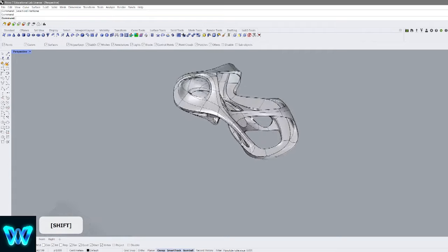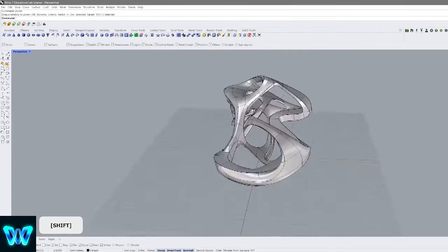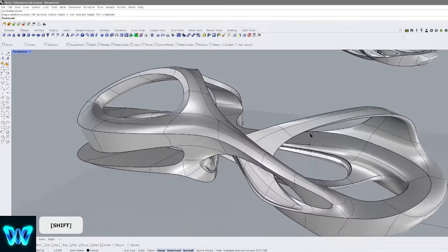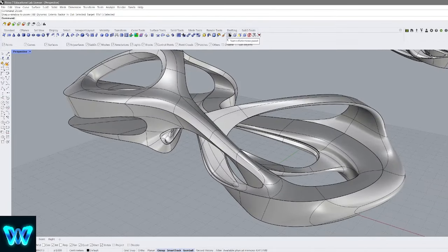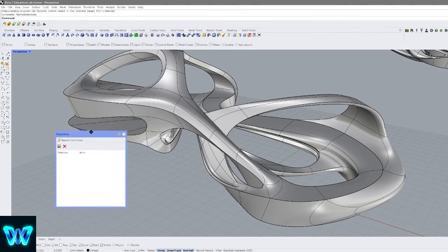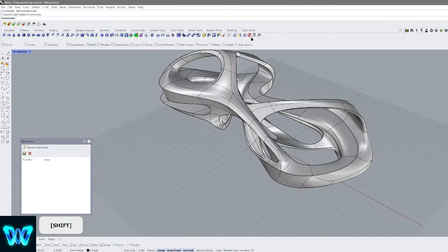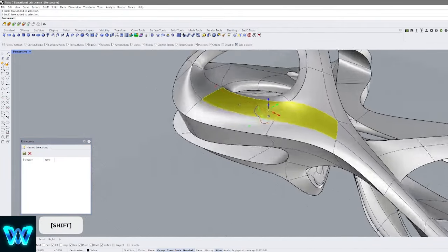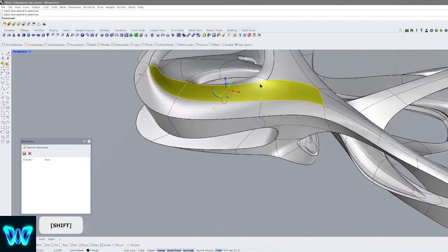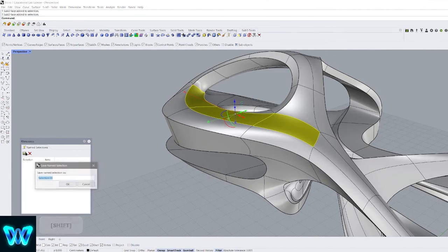The last thing about SubD that I want to mention, which is really, really useful if you're creating very, very complex and big models, is this right here, which is named selection panels. The moment you open it up, it's a new panel. And what you do here is that you can start selecting faces in SubD, specific faces, specific corners, specific edges, and you can save these selections. So I can save this right here and call it selection 1, S1, right?